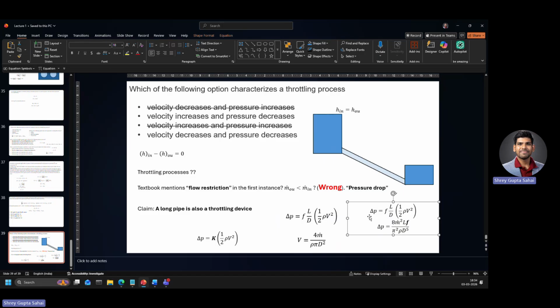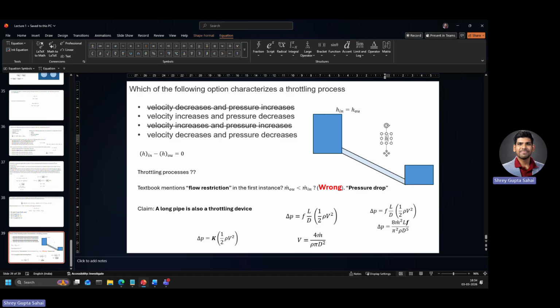So we have three conservations, right? In thermodynamics, you generally don't look into the momentum conservation. That is what fluid dynamics is for. But once you solve the energy conservation of these throttling processes, you see that the enthalpy at the inlet and the outlet should be equal, but the pressure should drop. Now, what happens for an ideal gas? So if your H of T, this thing I told you, right? For an ideal gas, H is a function of only T.